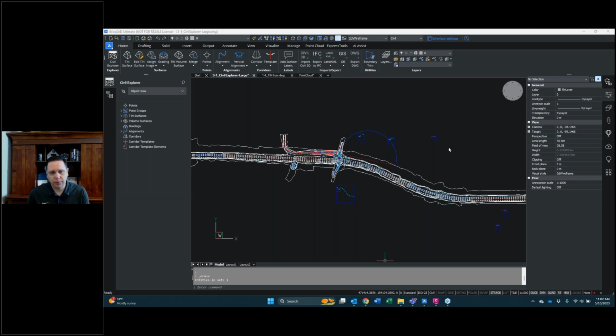But I've got a few things that I'm really excited to show you all here. Particularly, the main focus is going to be on building surfaces using these large data sets, massive data sets that may come from point clouds, any way that they would be collected, whether that is via flying for a LiDAR scan, using drones, terrestrial scanning, even bathymetric surveys. I mean, when it comes down to it, they're all just massive amounts of points, and how can we deal with those in a CAD product that maybe wasn't necessarily originally designed to deal with tens or hundreds of millions of points.